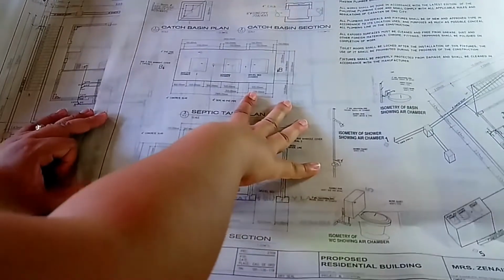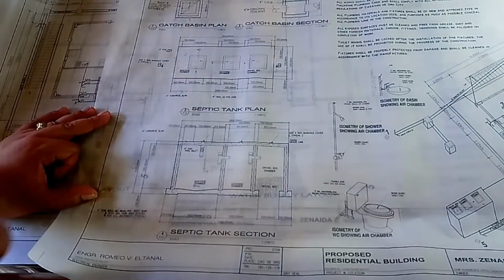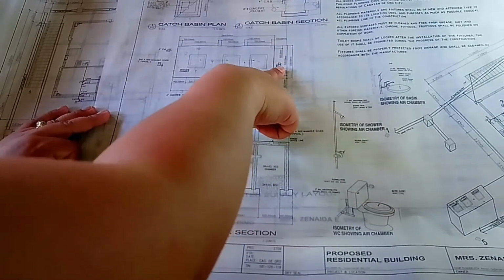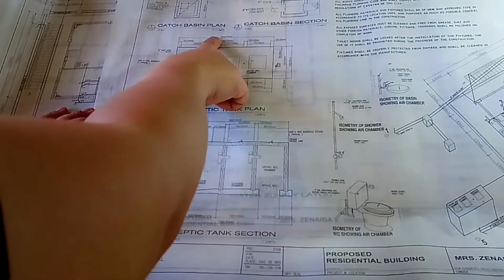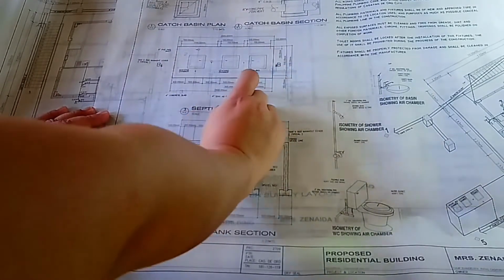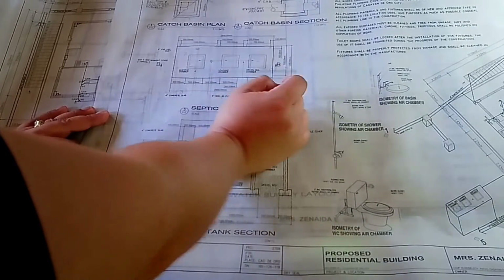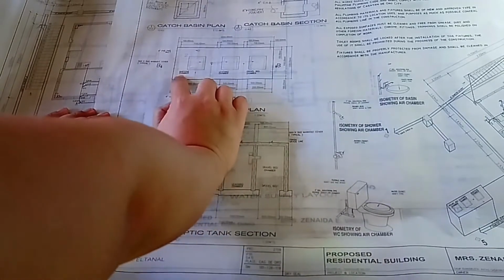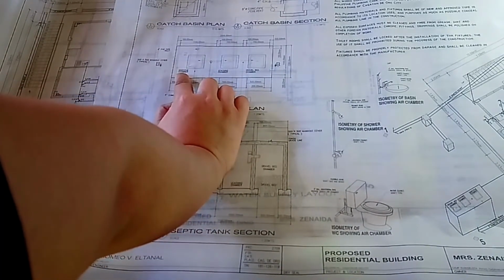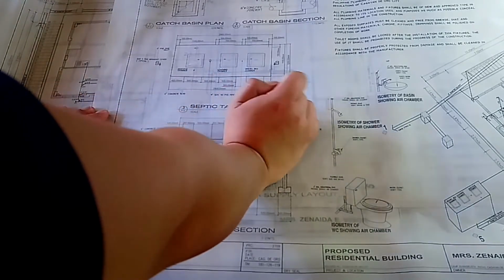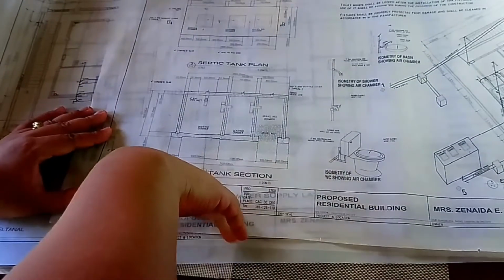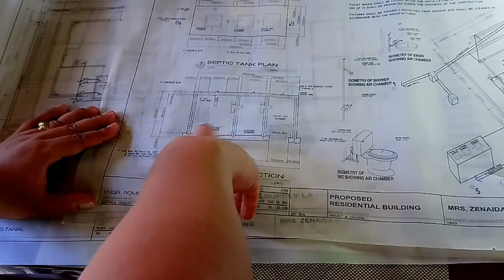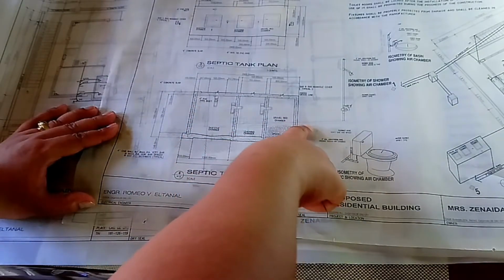Okay, then another important thing to do in your plumbing is to make your septic tank plan. Here you can see the size and dimensions, and also the manhole. So we have here the size is 2.9 by 1.2, which is the standard, and the size of the manholes, which is 0.5 by 0.5. So you see here your digestive chamber, the leaching chamber, and the gravel bed chamber. Okay, then you can see the septic tank section. So this is the section of your septic tank. Okay, here your digestive, leaching, and then the gravel bed chamber.